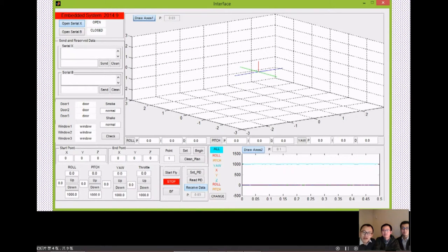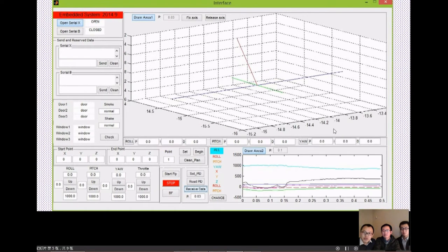In this part, I clicked the Open Serial Port button to establish communication. I periodically sent a 1 byte message and received 6 data, which are pitch, yaw, roll speed, and acceleration for axis X, Y, Z from the copter. I calculated the copter's rotated angles and moving distance using this data with the quaternion method. The pictures below are graphs of pitch, yaw, and roll speed and XYZ acceleration. I also drew a 3D picture for checking this copter's motion.